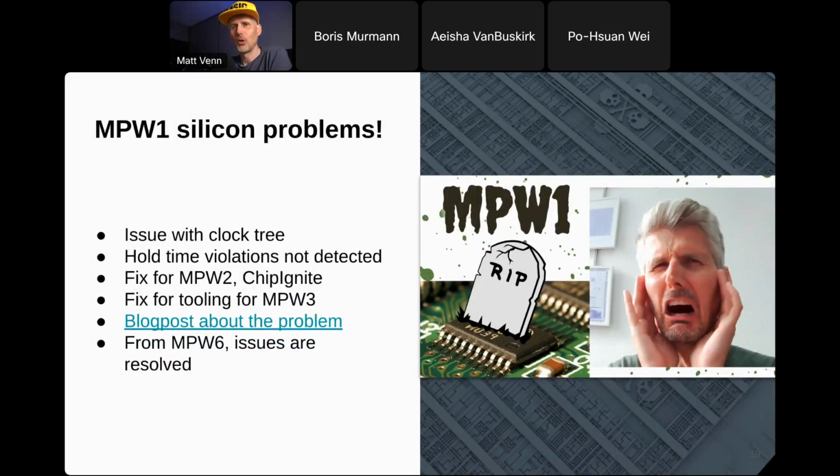So from MPW6 onwards, things got easy. But for MPW1 to 5, the silicon needed a lot of fettling to get working, which was a real shame because those early designs were very difficult to make measurements from. And I did get my stuff to work, but only by very, very careful control of the supply voltage and twiddling with the GPIO configuration.